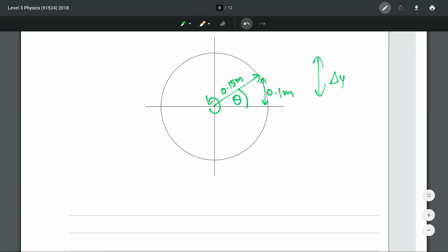Let me explain why. So we have our displacement, which is given by this equation here. I'm using the sine one since our spring we're assuming is starting from 0 displacement. Our velocity, therefore, is going to look like this, which is also on your formula sheet. Now, given that angular velocity is just angular displacement over time, that means that angle is equal to omega t, which means that we can replace our omega t here with just our angle, which is why we're so interested in it.